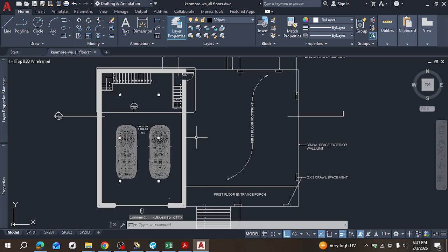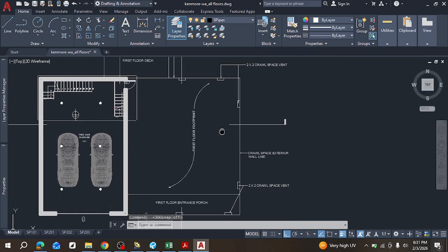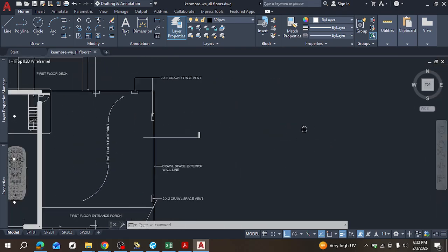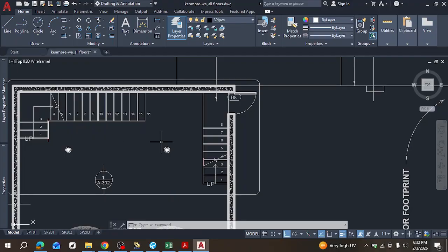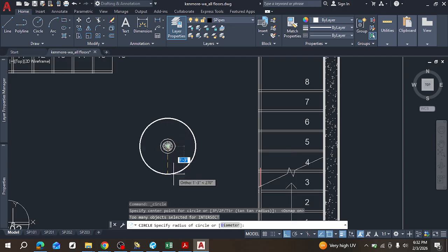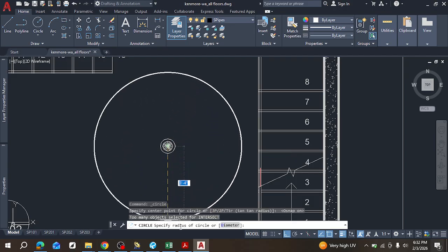So for this, each sprinkler here, we set it to use a radius of 7.5 feet. Let's say we have a sprinkler here. Let's draw a circle of coverage from the center. Okay, turn this back on so I can easily click to the point, right? They're asking us to specify the radius of this circle, or they want to specify diameter. When drawing it, you can click this, but it's radius we need.